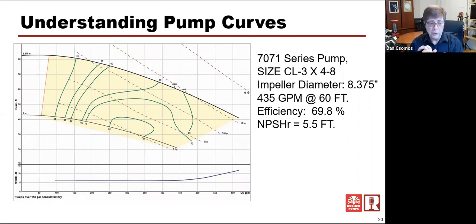Remember that if they tell you in PSI, you've got to confirm that it's water, and you should really confirm approximately what temperature that water is at, because that's going to tell you certain things like NPSH concerns, and it's going to tell you the specific gravity of that water, because it varies a little bit, not a lot. At 180 degrees, water is lighter. It's getting closer to boiling. It's lighter per volume per gallon than it is at 60 degrees or 40 degrees.